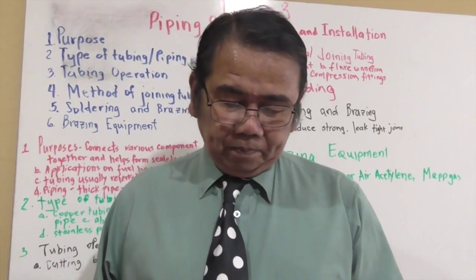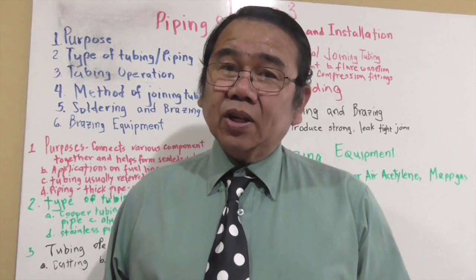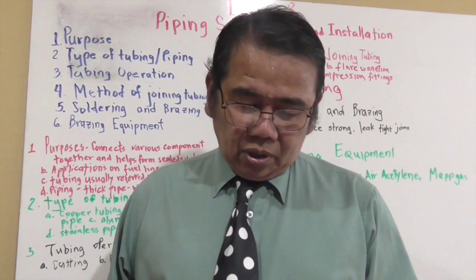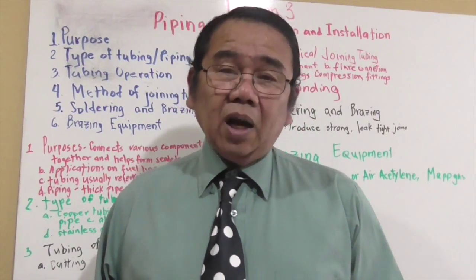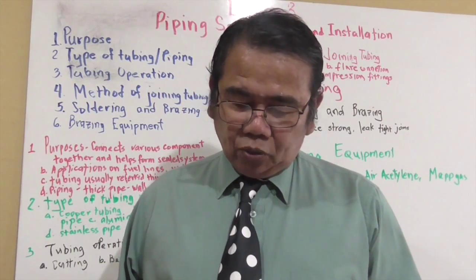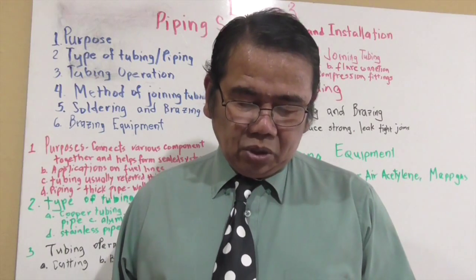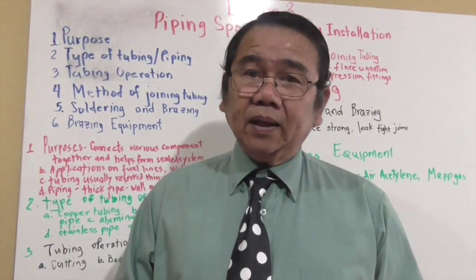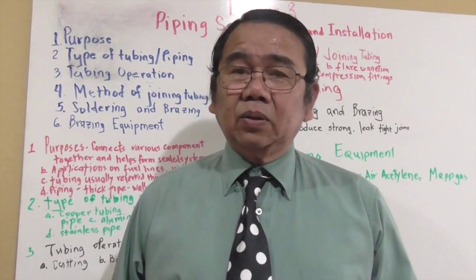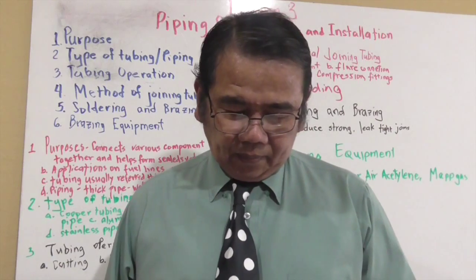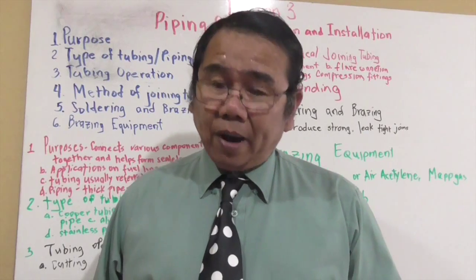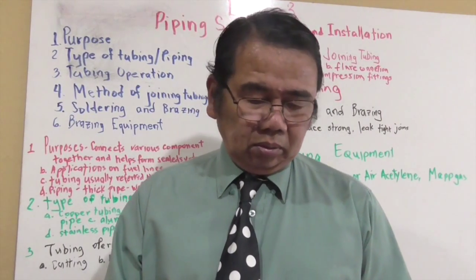Ensure tubing or pipe is cut squarely. A sawing fixture may be used to accomplish this. Keep saw filings from falling inside the tubing or pipe. Be sure to deburr the tubing. Deburr means you remove the extra material at the end of what you cut. Be sure to deburr the tubing or piping inside and out.